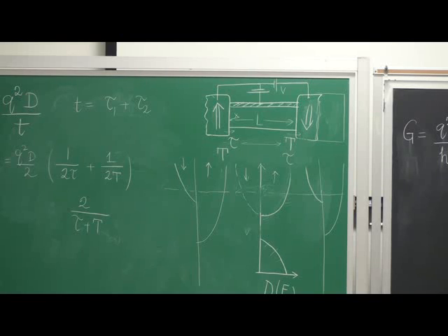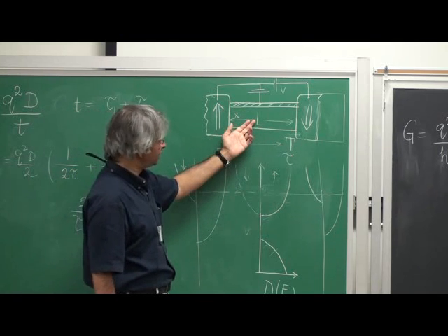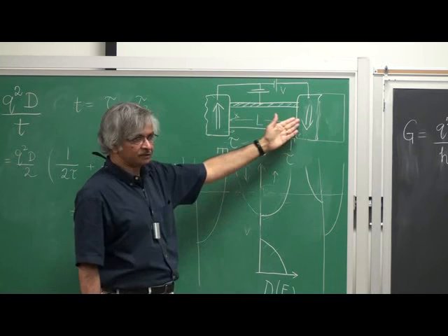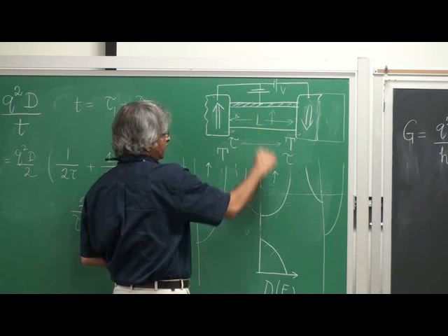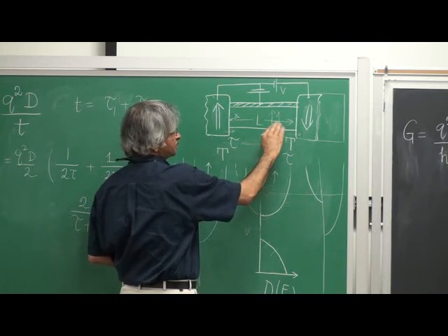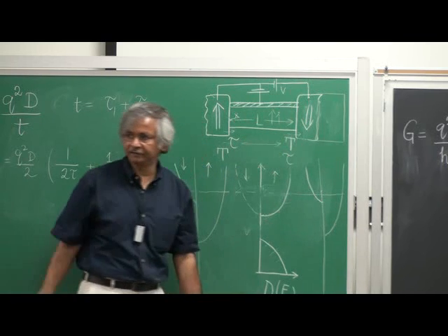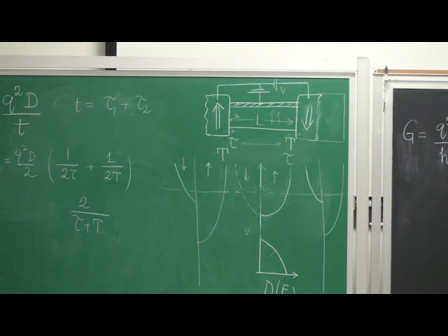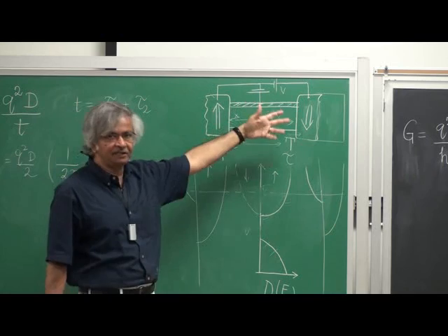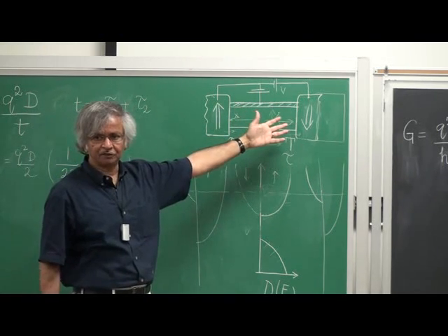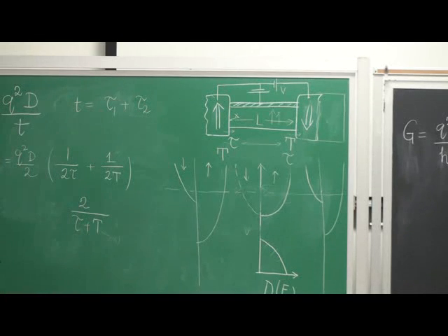Because as I say, 10 years ago if you asked someone, how do you turn a magnet? Well, you turn it the 19th century way. You put a magnetic field. That's the only way to do it, run coils around. But now I'd say there is clear experimental evidence that you can actually turn it by just running spin currents. In other words, what you're doing is you're injecting spins from here. This injects electrons with one preferential spin, and enough of them get in here that they actually turn that. That's now demonstrated. And what that means is, again, now lots of interest in this, because you not only can read information, you actually can write information also.